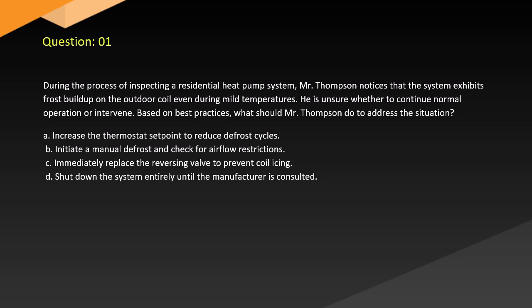A. Increase the thermostat set point to reduce defrost cycles. B. Initiate a manual defrost and check for airflow restrictions. C. Immediately replace the reversing valve to prevent coil icing. D. Shut down the system entirely until the manufacturer is consulted.